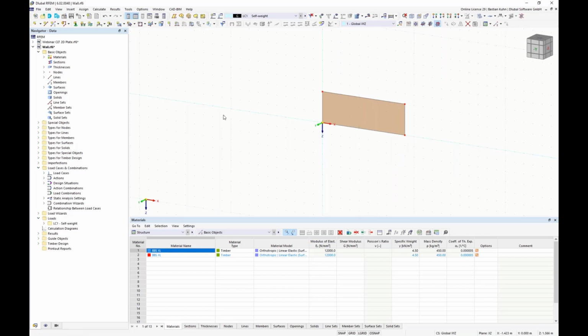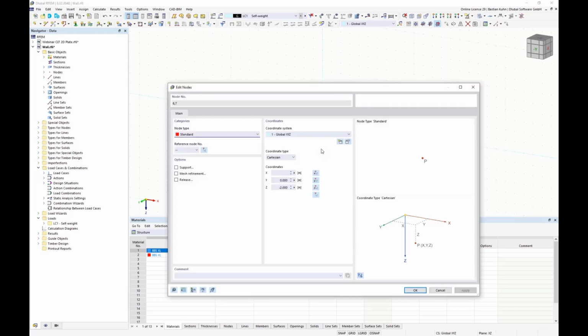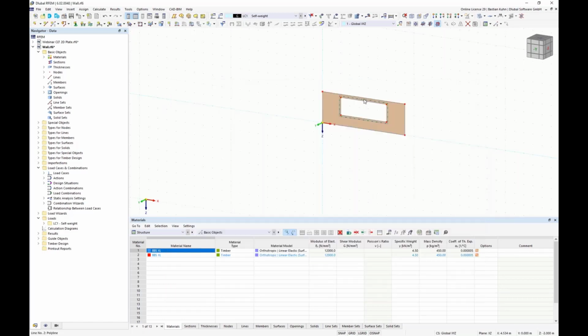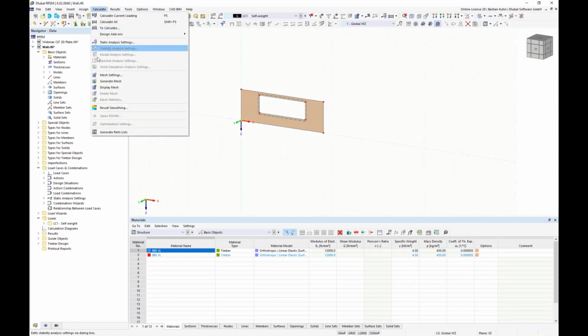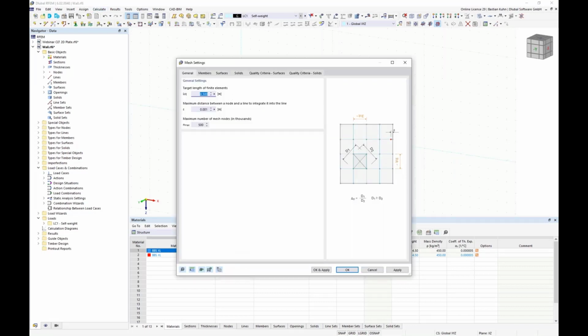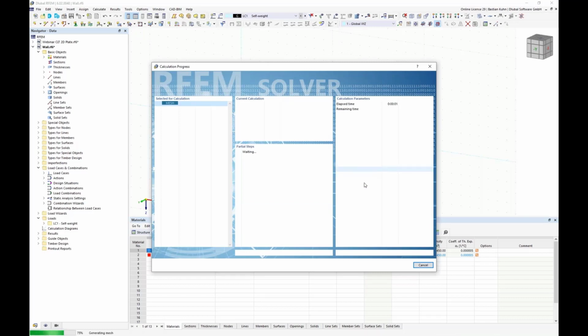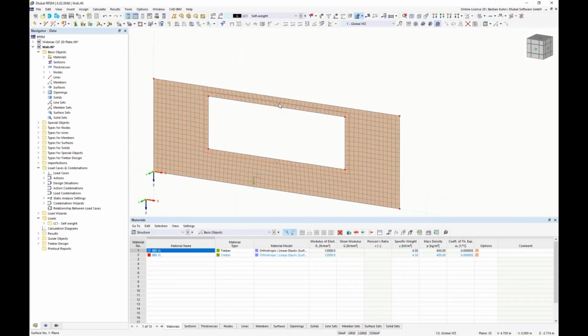So okay, we make it a wall, give it a little opening, assigned here by this, just to have it symmetric. Oops. And in order to see something there with the shear problematic, because that's the only reason I'm showing you this example here, we make it quite narrow here on the top. And because it is this kind of narrow, I have to refine my FE mesh in order to have at least 2 elements over the height of this little spandrel in here.